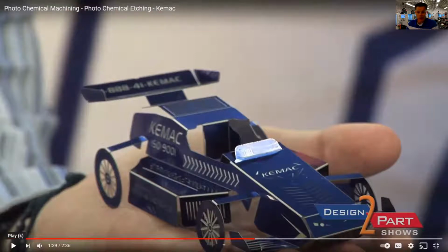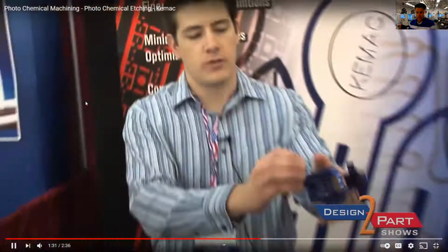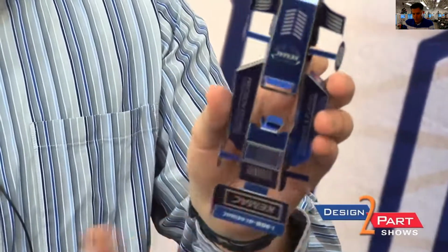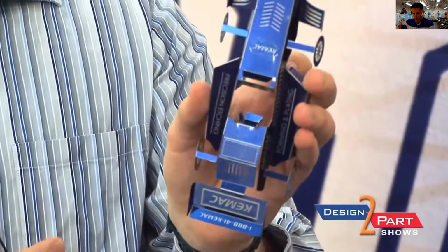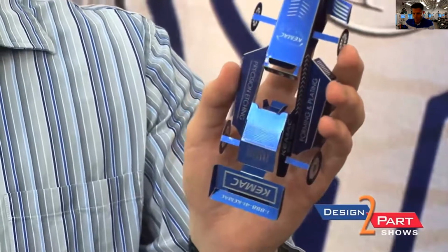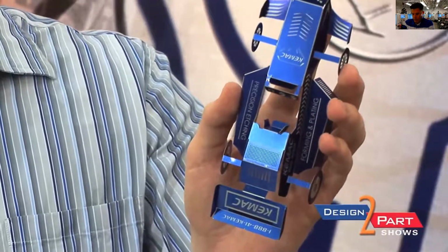They left the photoresist on it, but wherever there isn't any material or any blue, it went ahead and etched away that material. So they etched bend lines into this and everything, so it was easy to bend up even. The advantage is if you don't mask the backside, but mask the top, we can do a half etch process where we just eat halfway through the material. This can be advantageous for flow channels or putting your part number in the part during our standard process.